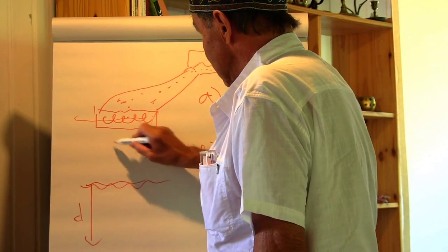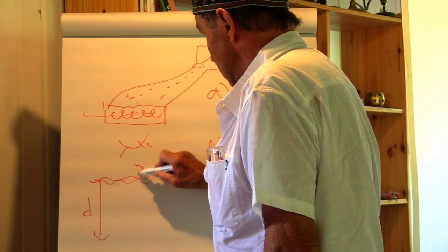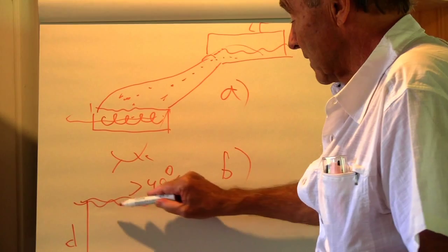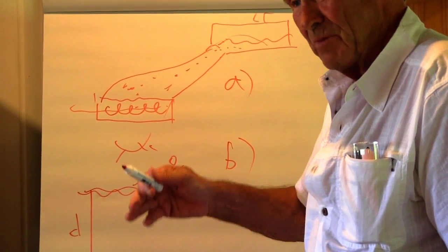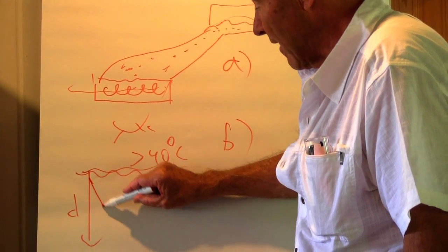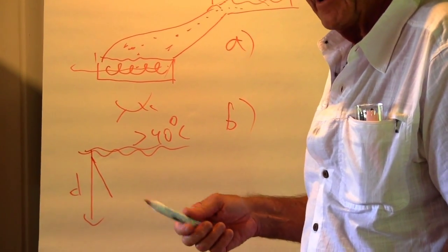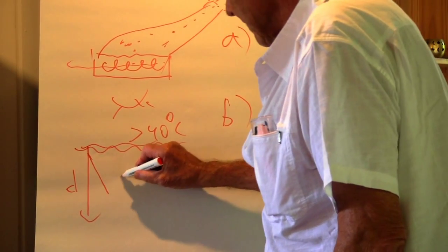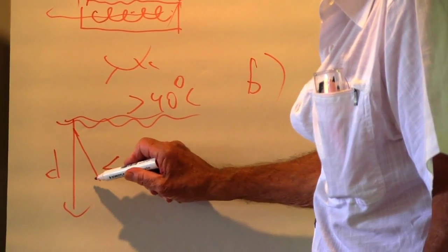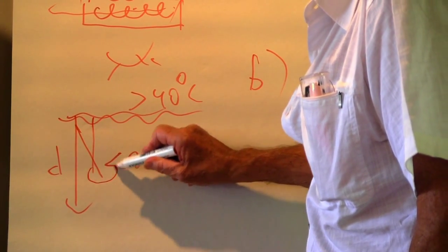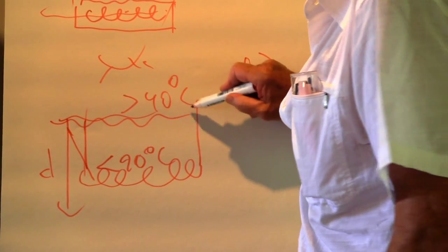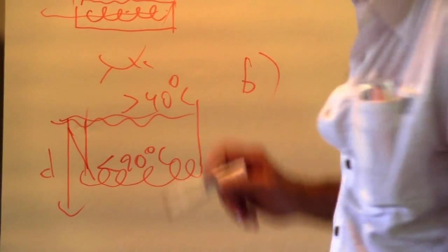So surface very hot in a hot country, but since the heat conductivity of the soil is very poor, in 4 or 5 meters you already find temperatures which are much smaller than 20 degrees centigrade. So you have to bring a coil in it, and you are cooling the engine with an underground coil.